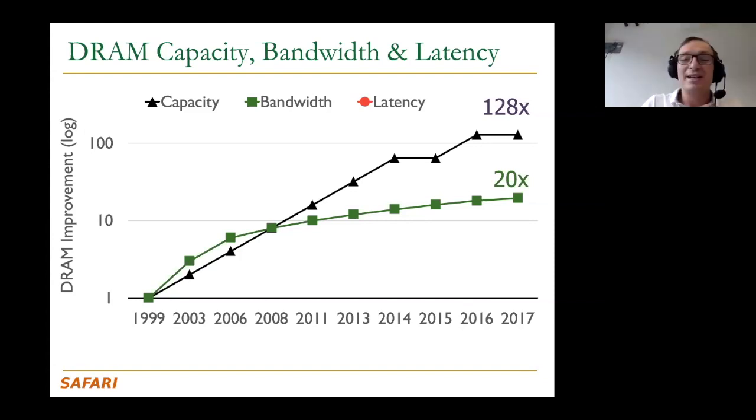So somebody asked, are we talking about a single channel? Basically, we're not talking about multiple channels. We're talking about a single DRAM chip. If you take the DRAM chip and the raw bandwidth provided by that chip, we're looking at the raw bandwidth and the raw capacity. At the system level, it's a totally different thing. You can build a system that has much more bandwidth by adding more channels, of course, yes, sure. But the single DRAM chip's bandwidth is not improving as fast, okay?